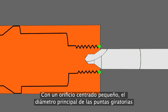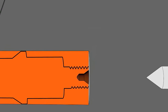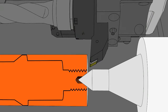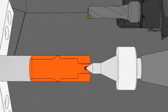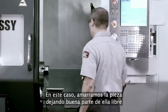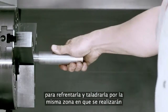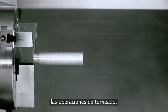The small center hole will also keep the live center's main diameter farther away from the end of the workpiece, since the live center doesn't sink as deep into the part. This provides additional clearance for the cutting path of the insert. But before center drilling, we need to prepare the end of the workpiece by facing it off. In this case, we grip the part in an extended position in order to face and center drill the part in the same place where the turning operations will occur.